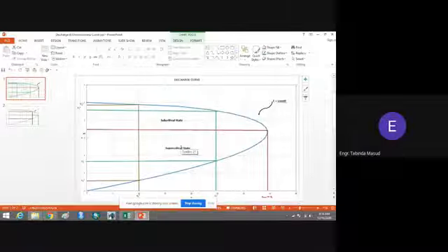And this curve shows you that for every value of the unit discharge, you have two depths of the flow, y1 dash, y2 dash, one of which is in the subcritical state and the other is in the supercritical state.